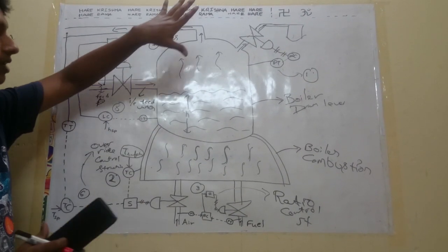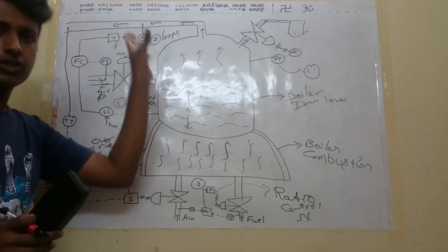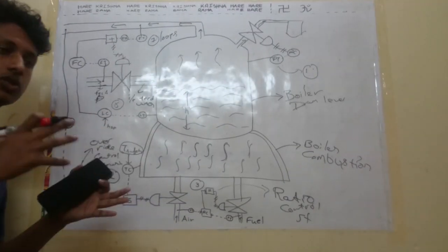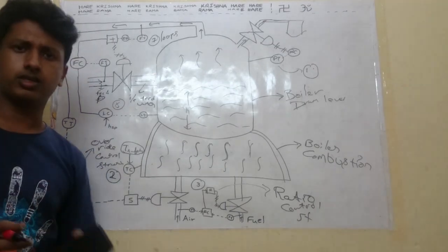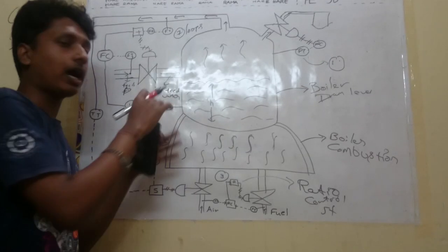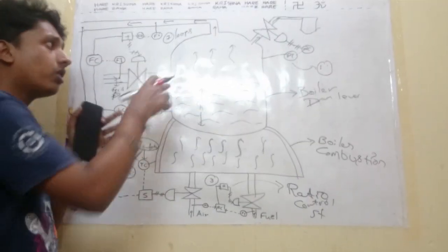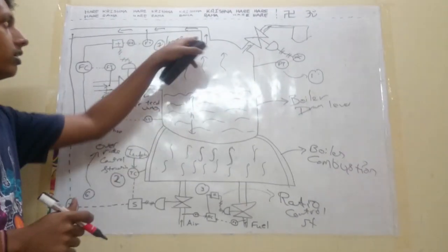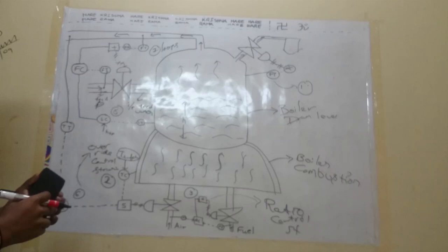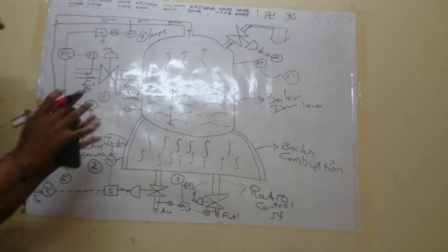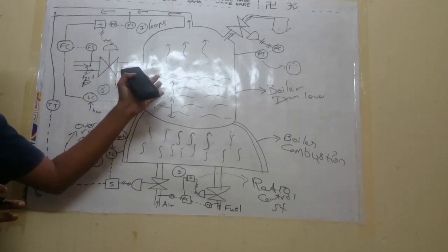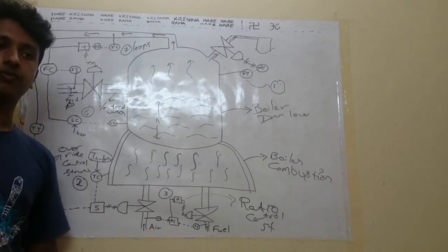Using this application, we are generating steam which will be useful in heating applications, like generating electricity or other heating applications. For generating steam, we must control the height. So our main control objective was not the steam, but the height. The steam is actually described as a disturbance. So we have discussed everything briefly and in a good manner. These are the boiler drum level control and boiler combustion control.